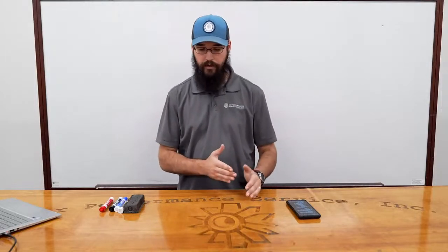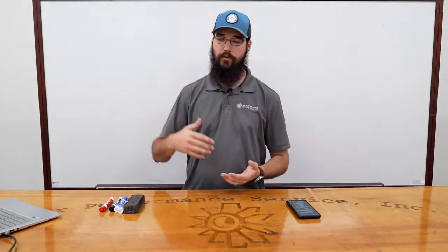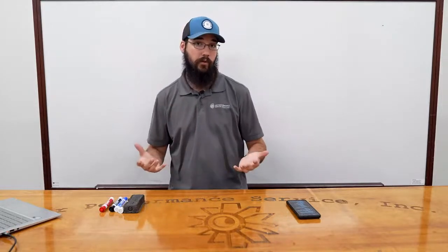So on an RTU, we may be moving 2,000 or 10,000 CFM, depending on the general size of it, whether we're talking a 5-ton RTU or a 20, 30, 40 ton. And most of the time, those would be considered constant volume, and we don't need to dive into the variable side today.